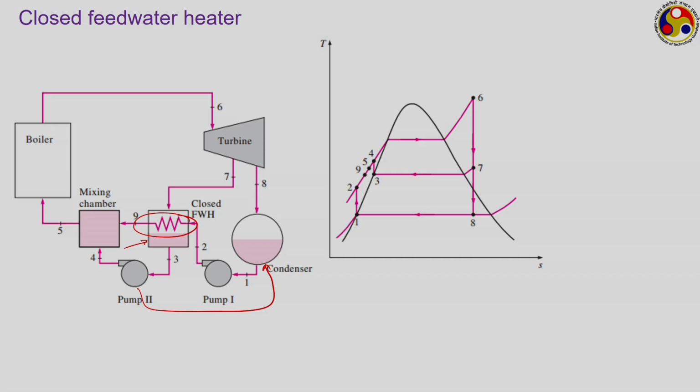Quite often the condensate formed from the bleed stream is just allowed to flow back to the lower side, to the feed water heater which is operating at the lower side. In that case, we do not need a second pump, we rather use something called a trap.